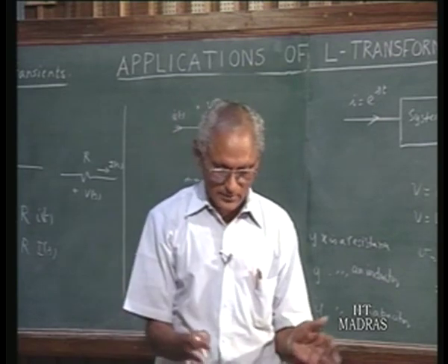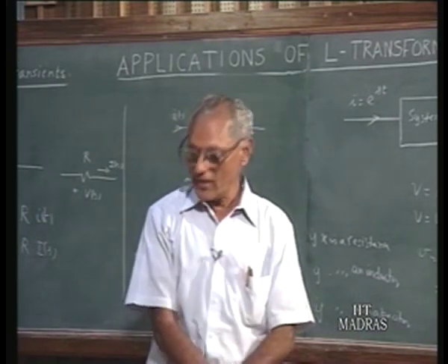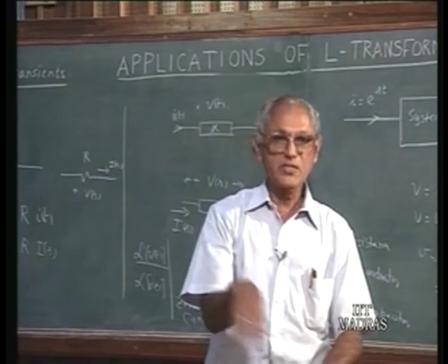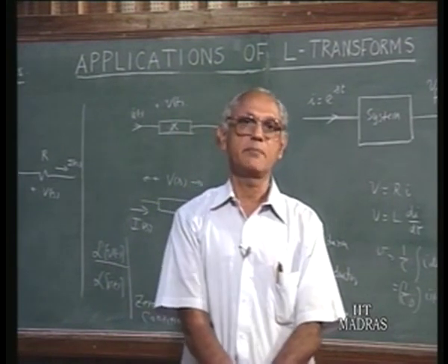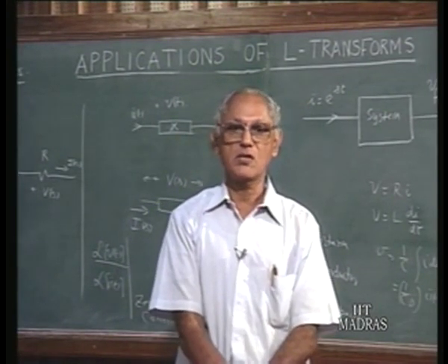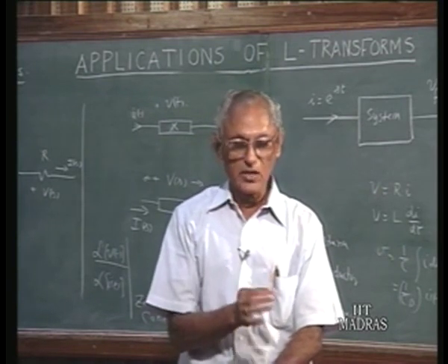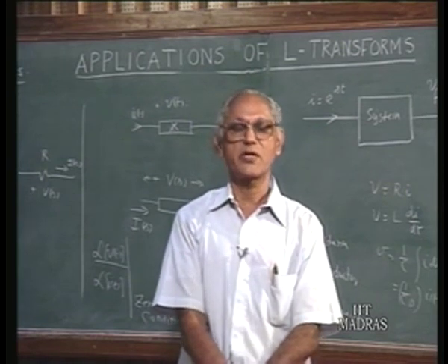We have a general circuit that is given to you. So instead of dealing with i(t) and v(t), sinusoidal voltages and currents, we represent in the circuit diagram the impedances of the various elements, j omega L, 1 over j omega C, as the case may be. And instead of the raw currents and voltages in time domain, we represent them by means of phasors.